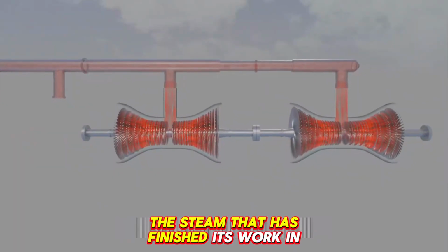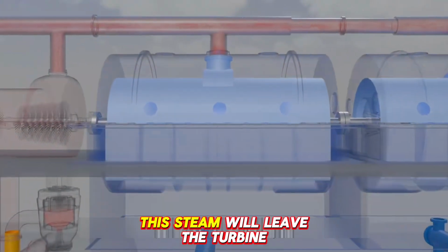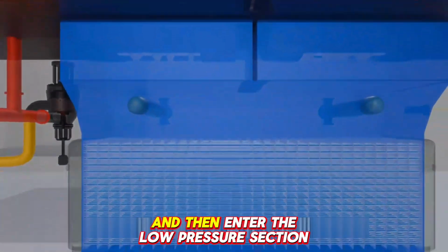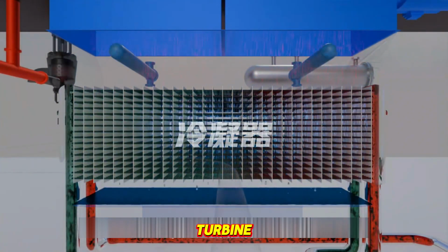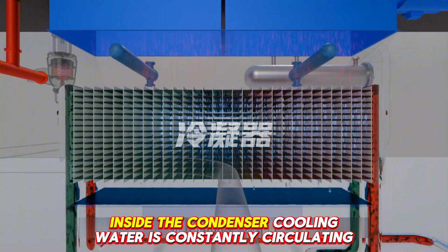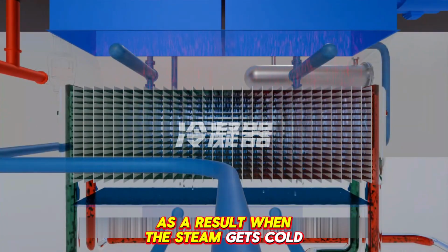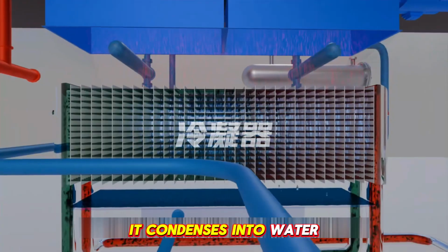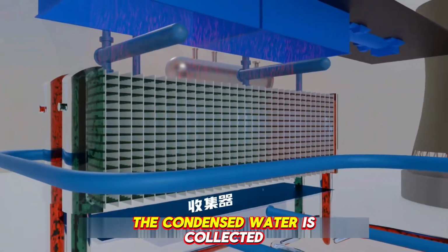The steam that has finished its work in the low-pressure turbine is not actually wasted. This steam will leave the turbine and then enter the condenser at the bottom of the low-pressure steam turbine. Inside the condenser, cooling water is constantly circulating. As a result, when the steam gets cold, it condenses into water. Then, through a collector at the bottom, the condensed water is collected.